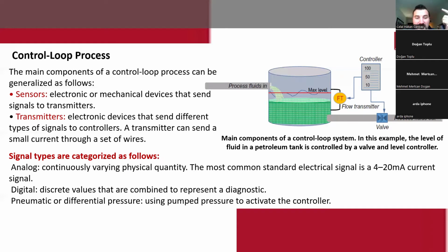Why do we need this? If the tank is full, it creates back pressure through the degassing stations. When oil comes up to the well sites, it makes back pressure and creates a reverse effect, and you cannot produce anything in this case. So I don't want my tank to be full, all right? Because of that, you have to be very careful. Sensors are making things easier by the day.